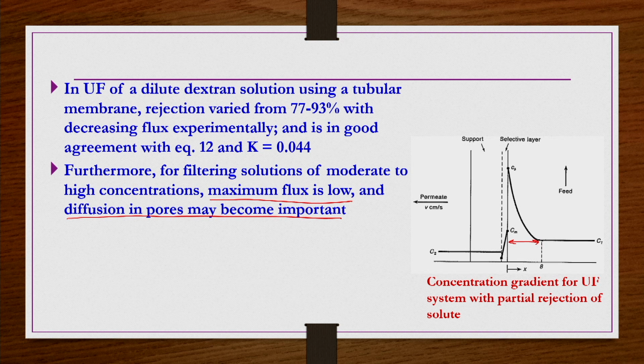But now this membrane layer, the selective layer, has a certain thickness, maybe some microns. In this thickness, there are several pores. In the pores, if the diffusion is dominating, that part we have not taken care of while deriving the concentration polarization. So, under such conditions, what could be the equation for Cs and V, etc.